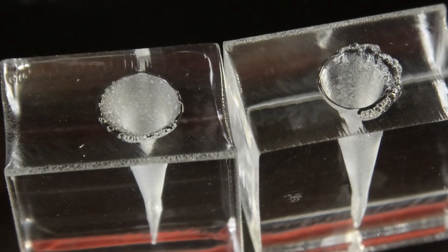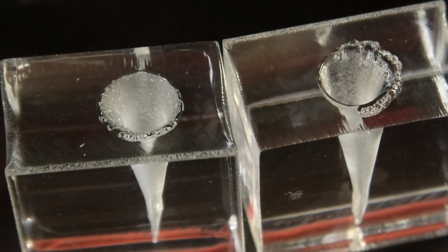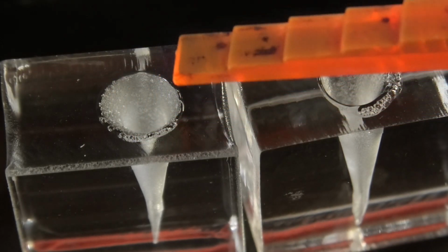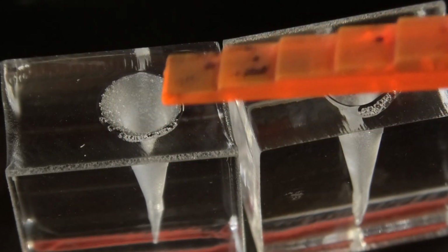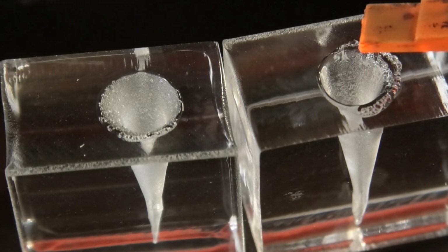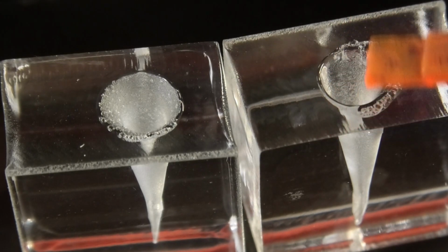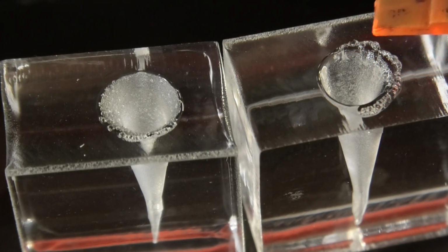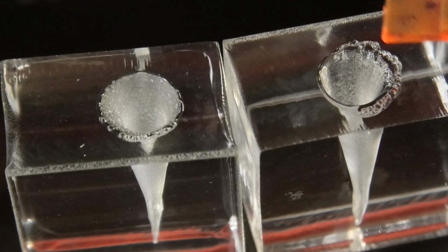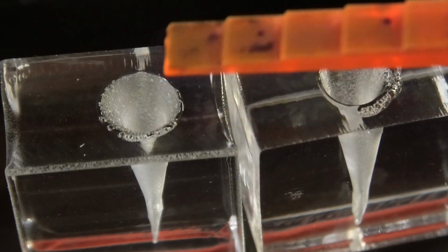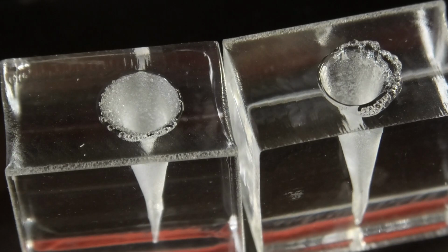So we compare that to my A grade tube. You can see here, we've got a very nice clean burn with a very small amount of low intensity effect around the edge of the beam. And as we move further on, the central core of the beam is still doing a good job, but the outer part of the beam is causing bubbling around here, which is technically increasing the beam size, but the core of the beam is actually remaining pretty constant. Let's go and have a look at the specification for these tubes and find out what's going on.